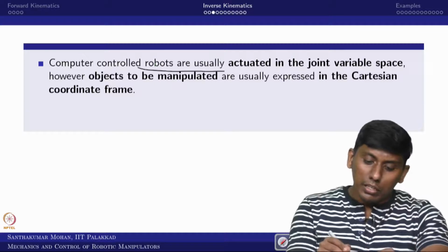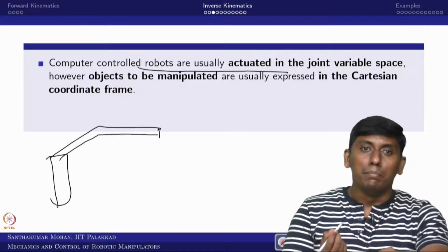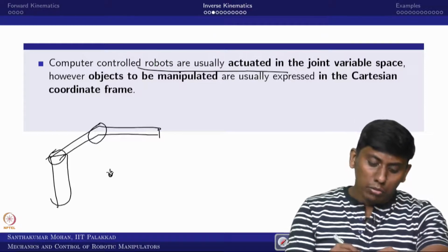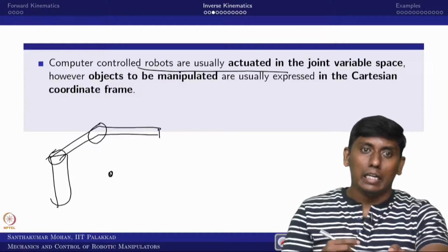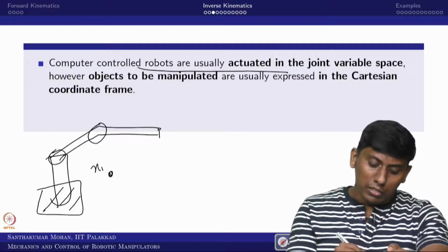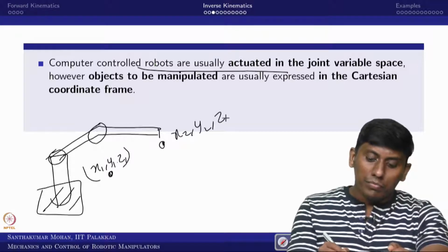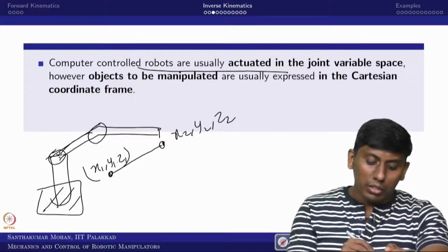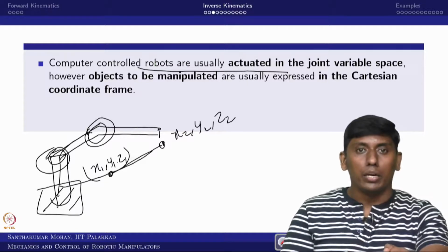Okay. So now we will think about a robot. I am assuming that it is a simple articulated robot, something like a SCARA robot. I want to reach this point. The robot will not know, right. So indirectly, inside the controller somebody has to feed it. What the user would be giving is x1, y1 and z1. So this needs to move to x2, y2, z2. This is what is given, and even the path would be given. Then what you have to do is see what inverse kinematics can do, so that you can see the individual joints and move them accordingly. Okay.